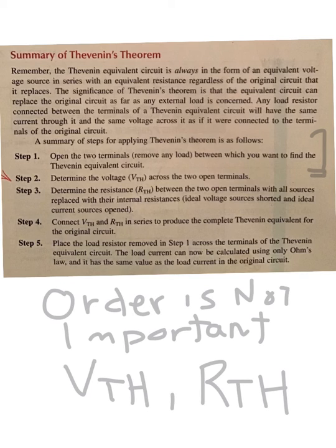When you remove a resistor from a location, let's say it's a 1K resistor, that 1K resistor changes to infinite resistance at that location, and a voltage will form there. That is what we're going to be solving for. It will become cleaner and clearer when we practice a few problems.